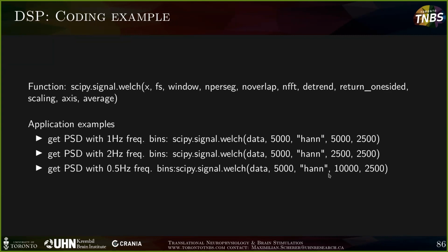Yeah. And since you want to average across that, if you select a high number here, and considering the data is more sparse, you're going to need substantially more data if you want to increase the frequency resolution much lower than 1 Hertz usually. Whereas decreasing the frequency resolution to 2 Hertz, 4 Hertz, or 5 Hertz, or something like that, can, if applicable, significantly reduce the amount of data you need to get a solid estimation out of your FFT for PSD.